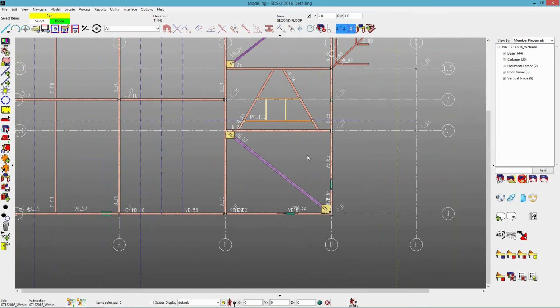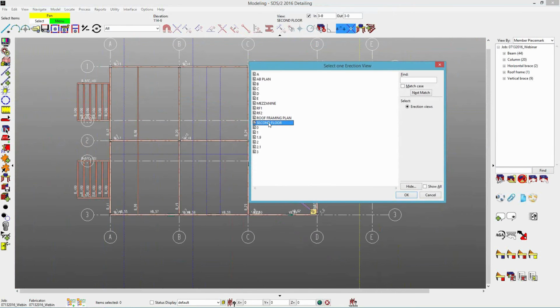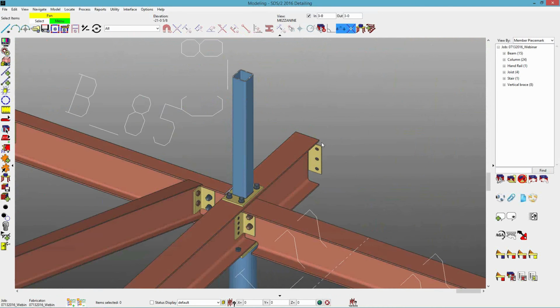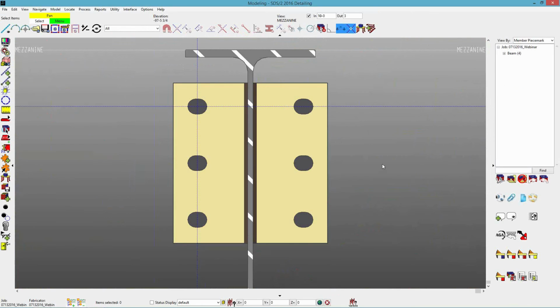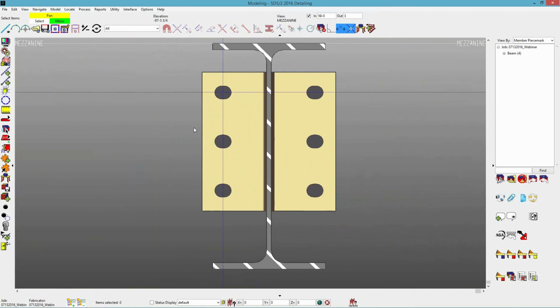And I mentioned that you can add these in modeling as either materials or as miscellaneous members. I just have a couple real simple examples here. So over here, I have an end plate, and maybe that's framed into a concrete wall or whatever it is to add my expansion anchors in here.